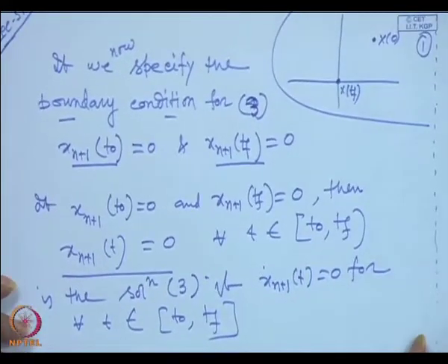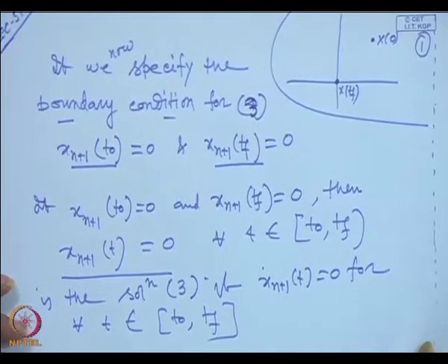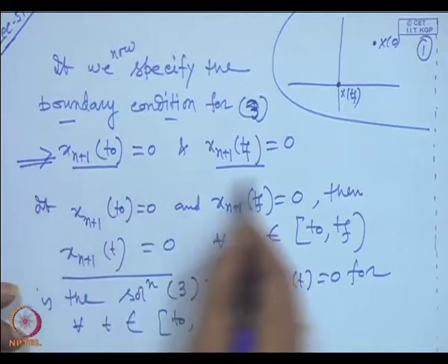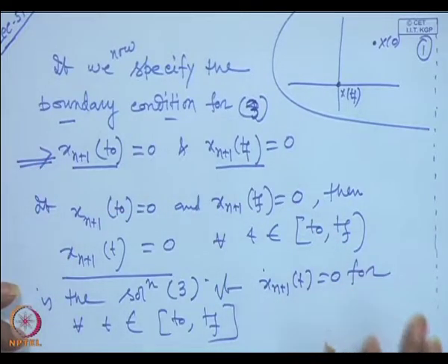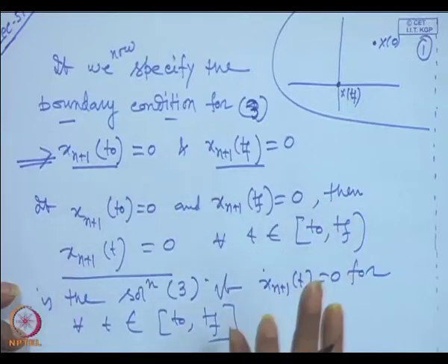So the solution of that problem, along with the state equation constraint and the additional boundary condition, we will be able to solve the problem. Which problem? Given the state equation, we have to minimize the performance index, meaning minimizing the control effort or control energy, subject to the constraint on the input as well as the constraint on the state.